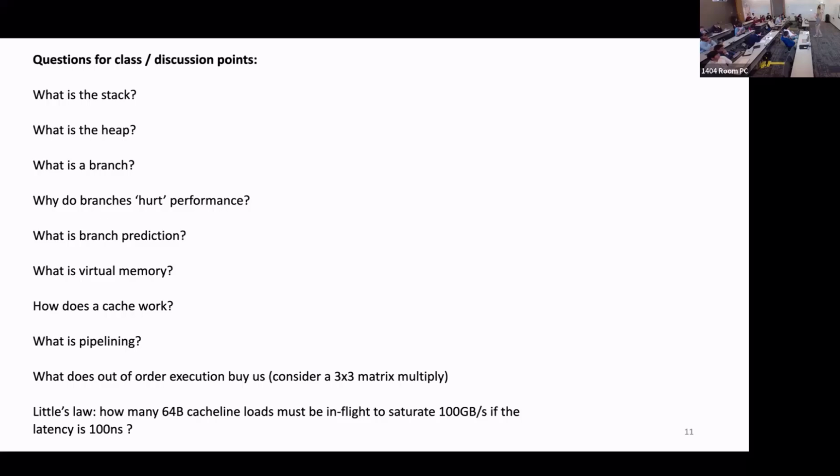Yeah, I could go into a huge amount of detail here. There are different types of caches. There's write back caches, and most people in the industry follow this thing called MESI, a cache protocol for handling multiple chip coherency. IBM does it completely different. It has write through caches and what I call back invalidate as the coherence protocol. And I got very immersed in that, the Blue Gene project, as you can imagine. But they have different scaling properties and so on.